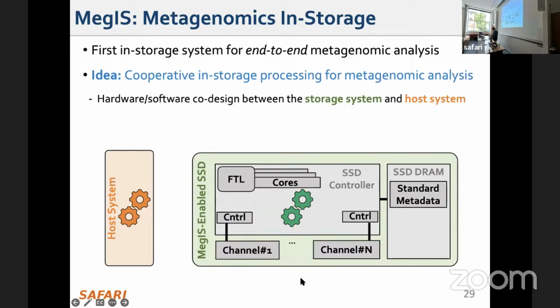And you can see some example of the storage system better over here. It's complicated, basically. In an existing storage system, you have a bunch of cores. You have the flash translation layer, which has specialized hardware, and you have the controllers, which have specialized hardware, and you have a DRAM, which stores some metadata, and you have the real flash chips over here, essentially. So when I said it's a system by itself, you can see that it's a system by itself with accelerators specialized for storage, general purpose cores, and actual controllers for flash, and then DRAM and controllers for DRAM, which is not shown over here.